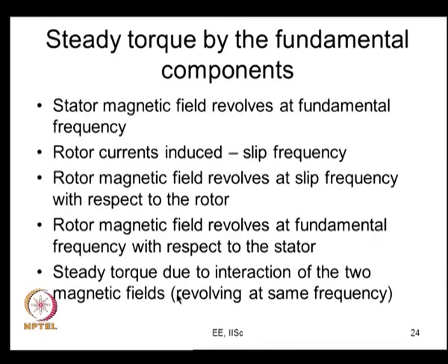So, when you talk of sinusoidal operation of the machine, or the effect of the fundamental voltages on the machine, what happens? The stator magnetic field is at the synchronous frequency, and the rotor magnetic field is also at the synchronous frequency. These two together produce a steady magnetic field, and a steady torque, due to the interaction of these two fields.